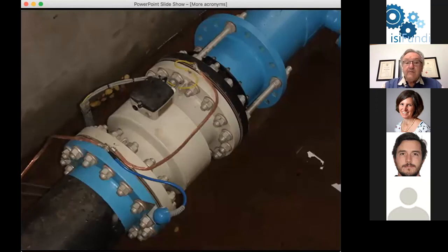Water pipelines have flow meters, and this is another perennial problem that we face because the flow meters sometimes do not get installed with the correct insulation. Again, you can see the heavy copper earthing cable that is necessary for the flow meter, and that goes off to the plant earth, and we need to make sure that the pipeline is isolated. And you can actually see the isolation kits or insulating kits, whichever you like to call them, on each side. And in this photograph, you can in fact see the insulating gasket that goes between the two flanges.